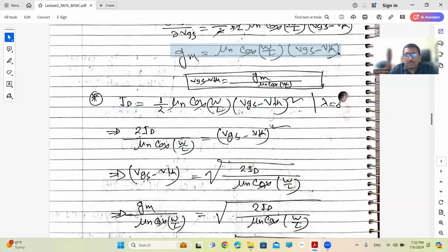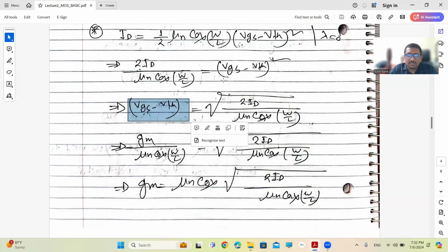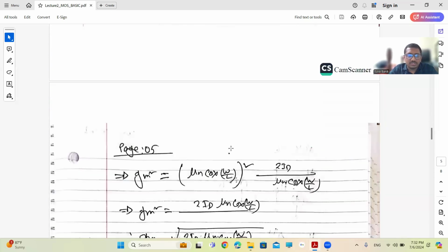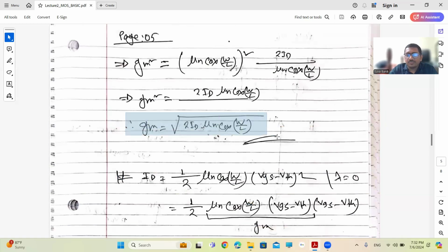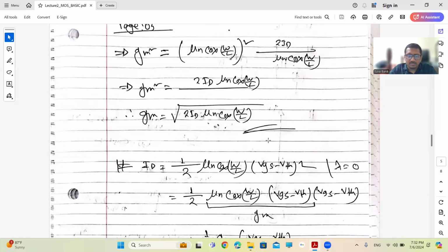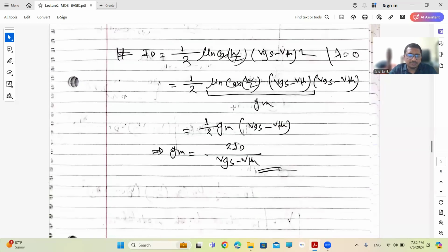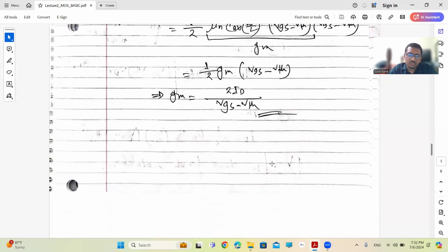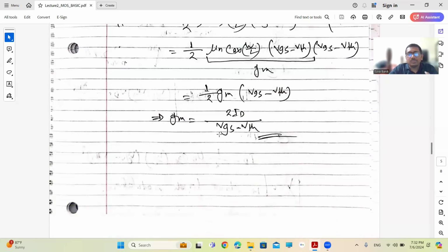So from here, what do we know? We can see that VGS is nothing but like this, right? We can use this. So from here, I just put this value in here. If we do some numerical calculation, we can calculate this one, right? How does this formula come about? If you are interested, I put it here. Again, we always start from this formula, and we know this term is nothing but gm, and we can also derive this formula, right?